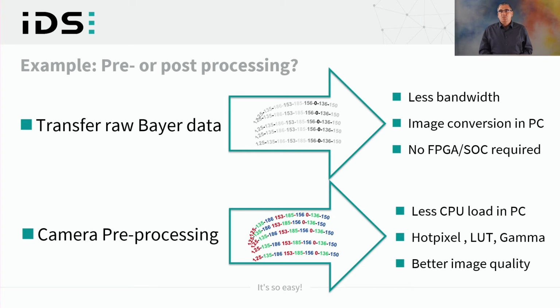Some sensors output 10 or 12-bit formats. Also, just 8-bit are required for image data output. The image data source for calculating thus can be up to 12-bit. Accurate calculating is performed with pixel data more than 8-bit. After calculation, the image format is cut down to 8-bit for image transfer. The source data base for Bayer color conversion in the PC is 8-bit raw data transferred from the camera to the PC. The source database is less accurate in this case.